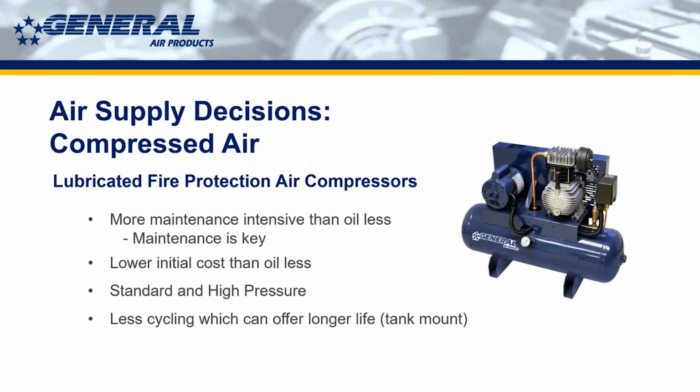And a quick rule of thumb when deciding between a lubricated compressor and an oilless compressor: the big decision maker is maintenance. Will there be somebody to do maintenance on site for a lubricated unit? If so, then I highly recommend a lubricated unit. Somebody's going to change the oil, make sure that it's anchored properly, and make sure that the motor and flywheel are aligned properly, things like that. And like I said, mainly the oil.